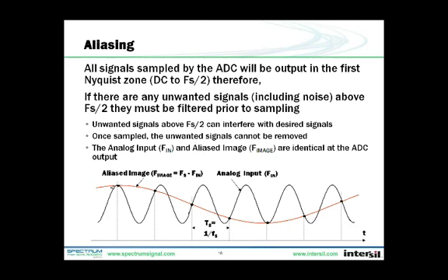The sample alignment relationship will happen periodically around every multiple of the sample rate Fs. This is why it's important to remove any undesired signals that might alias onto our desired signal before sampling, because after you sample, you can no longer separate these signals.